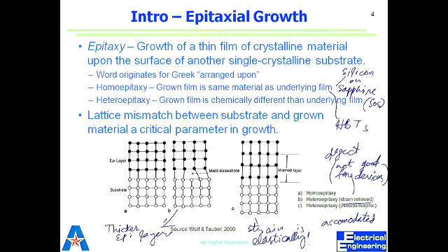So how do we get rid of those issues of strain? We have to make the epi layer thick. So when we make it thick along the y-axis, we lose the effect of that strain. At some distance, the single crystalline comes out of the strain. So that's what we have to do, make it thick enough. How does thickness help? How does it reduce the strain? Because when you go away from that interface, the effect of the strain reduces on the atoms.